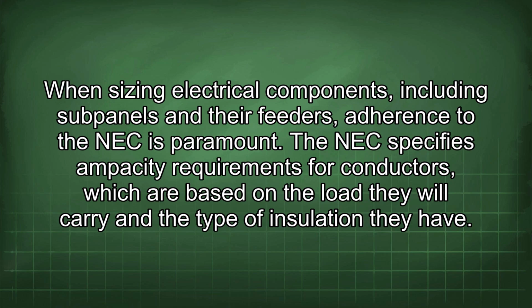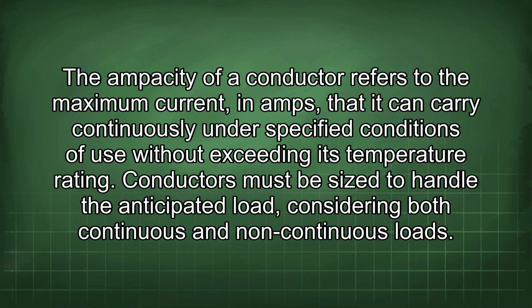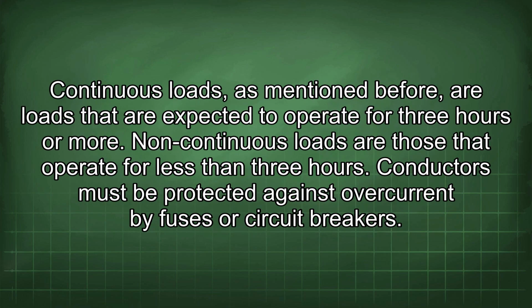The NEC specifies ampacity requirements for conductors, which are based on the load they will carry and the type of insulation they have. The ampacity of a conductor refers to the maximum current, in amps, that it can carry continuously under specified conditions of use without exceeding its temperature rating. Conductors must be sized to handle the anticipated load, considering both continuous and non-continuous loads. Continuous loads, as mentioned before, are loads that are expected to operate for 3 hours or more. Non-continuous loads are those that operate for less than 3 hours.